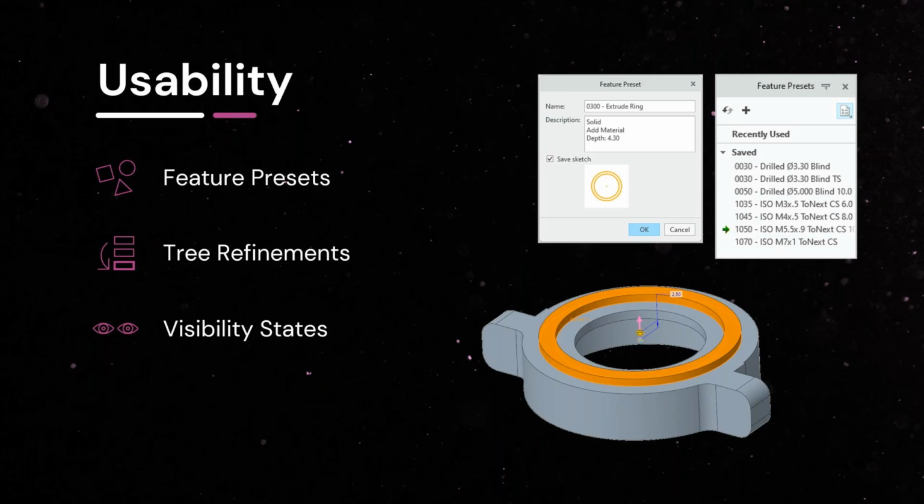One of the new features that's been brought into Creo 12, though, is visibility states. These are ad hoc states where you can capture the current visibility of your model. If you've gone into your model and hidden a load of components in an assembly because you're working on a particular area, there are situations where the state you're currently in is exactly what you need, but you want to then show a load of other information to go grab a bit of geometry, maybe copy a surface, and then you want to jump back to where you just were and have everything hidden again.